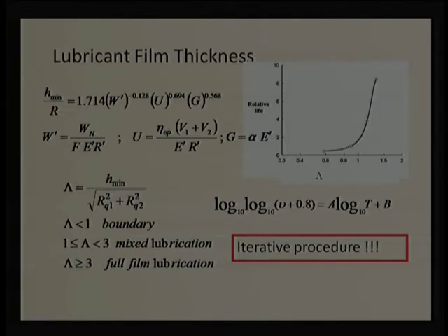We do not know the temperature; we have not discussed anything about the temperature. We are saying mu depends on the regime, the regime depends on the film thickness and surface roughness, film thickness depends on viscosity, and viscosity depends on the temperature. So, a number of equations need to be solved together. It is highly complex.